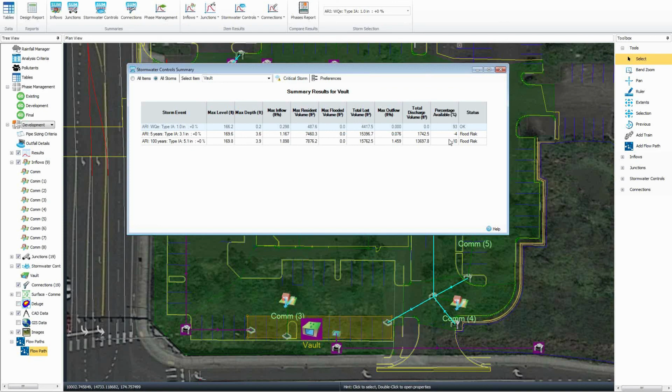In some facilities, this one might not be the case. You can fully fill this one up, but if it's a pond or a rain garden, you might not be allowed. There might be an ordinance against filling up to the brim, so to speak, so you might see something and go, you know what, I need to knock this back down to keep that water level below the freeboard.